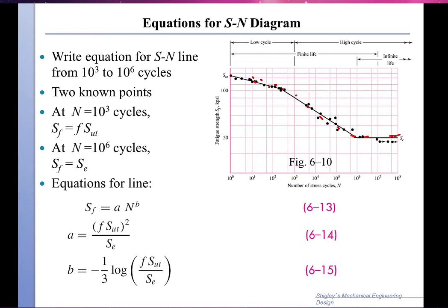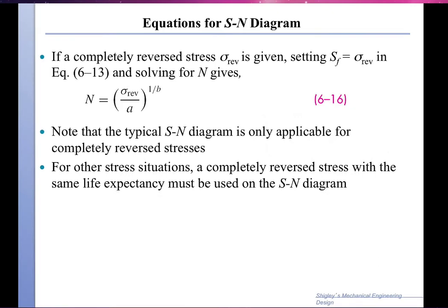The representation, which is a power representation, A times N to the power b, must have a log to the base 10 of S and a log to the base 10 of N. As you can see here, it's a log. So I misspoke when I referred to a linear log; it's a log. When you have a log representation of the graphics, you get a power relationship and you get straight lines on the log plot.